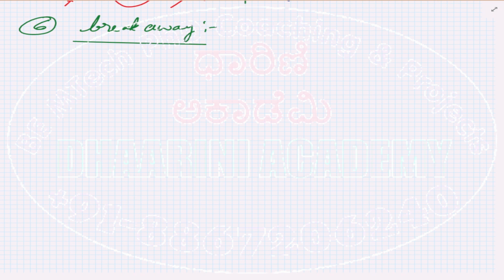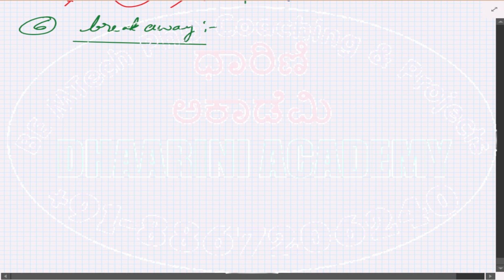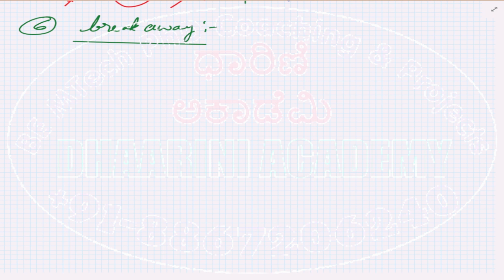Okay, now we know that the root locus always starts from a pole and is directed towards a zero. If you have a finite zero, in the sense that we can locate a real zero on the graph, the root locus which starts from a pole will go towards that zero. If you don't have a finite zero on the graph, we can assume that the zero is present at infinity and a branch will go towards infinity by using the asymptotes.